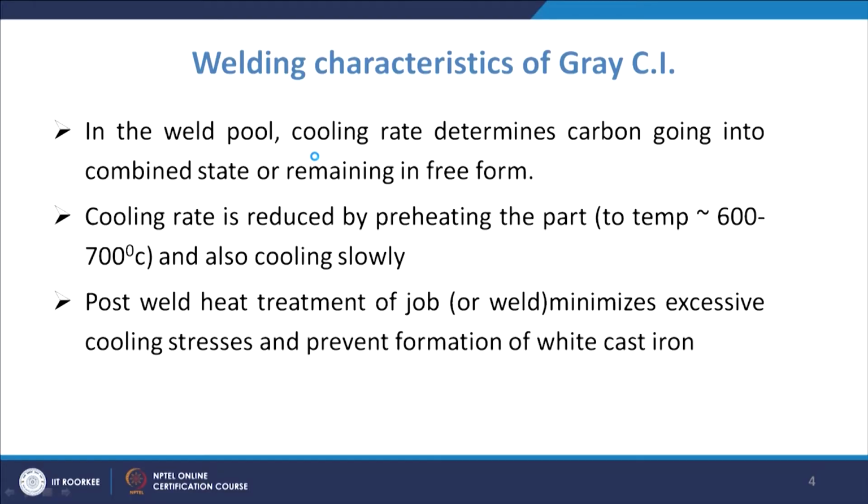Now, we will talk about the welding characteristics of the gray cast iron. In the weld pool, the cooling rate determines whether carbon goes into the combined state or remains in free form. As we know, when you increase the cooling rate, most likely the carbon will go into the combined form.